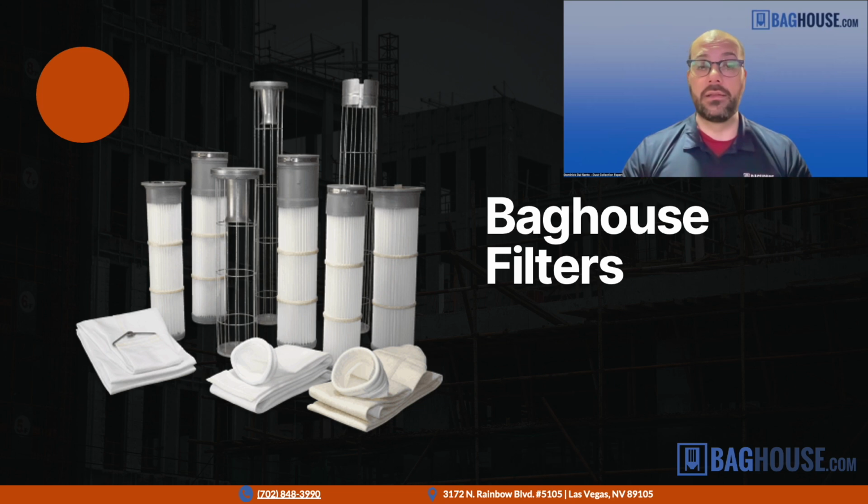Now, in certain spots, you might have a mix of chemicals, moisture, humidity, different things going on where you can have acid reactions. Now, in these cases, we might use a different medium that's especially resistant to those kinds of chemicals, things like acrylic bags, or maybe bags made out of PTFE felt. Now, a very common, I'd say the three most common additives or treatments we put on top of the filter media. We take, if it's polyester, aramid, or fiberglass, whatever the base media is. Very commonly, we will apply on top an acid-resistant finish. We'll also apply a hydrophobic, oleophobic coating that repels oils and waters.